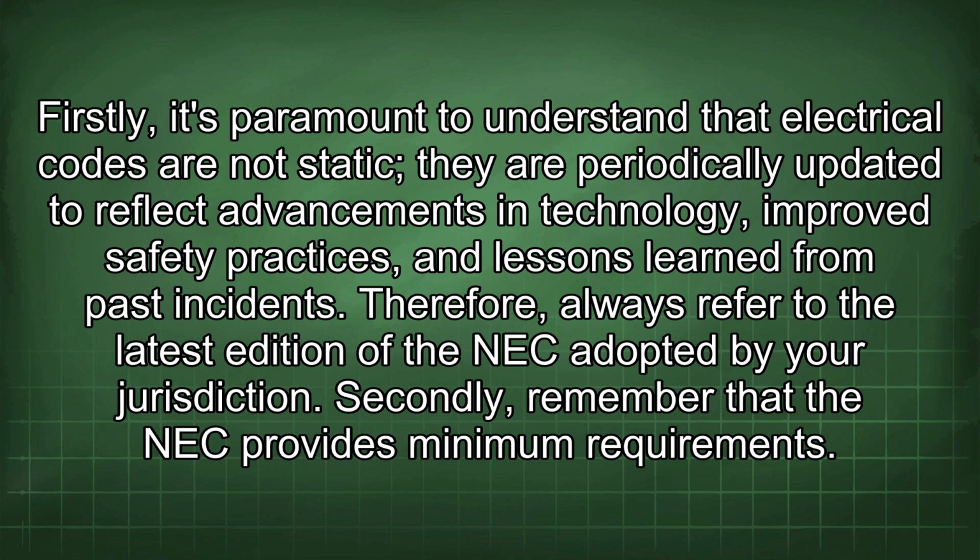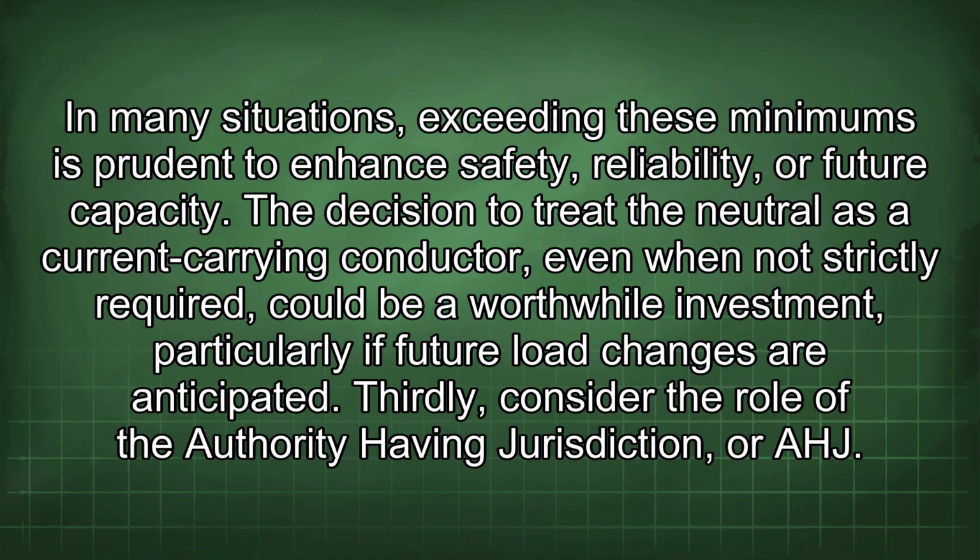Secondly, remember that the NEC provides minimum requirements. In many situations, exceeding these minimums is prudent to enhance safety, reliability, or future capacity. The decision to treat the neutral as a current carrying conductor, even when not strictly required, could be a worthwhile investment, particularly if future load changes are anticipated.